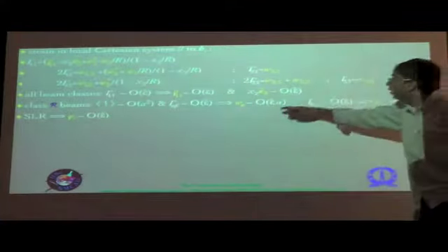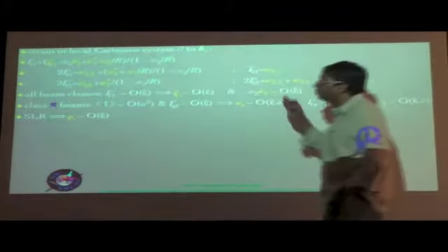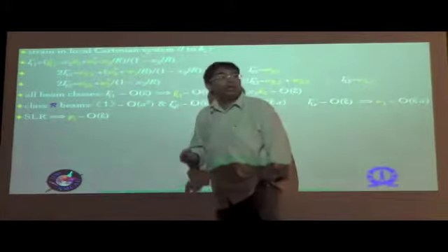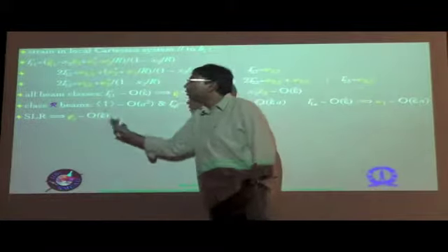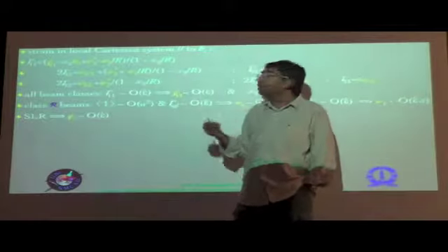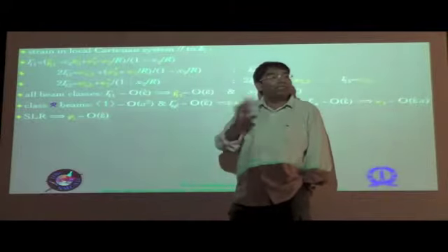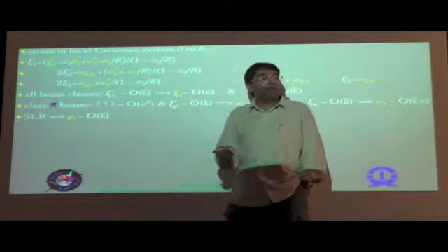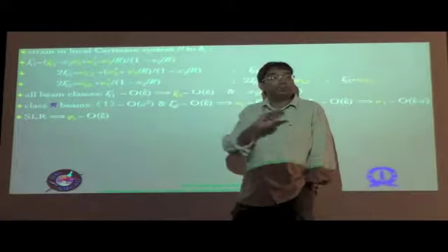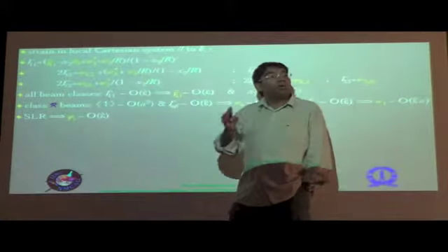So in other words, we can combine all of these. W alpha is of order epsilon hat A and W1 is of order epsilon hat A. So we can just write Wi is of the order of epsilon hat A, which is the case for class R beams. Next situation is the small local rotation, that is of the order of epsilon hat. In fact, this we already discussed in the general situation where we compared the orders of magnitude of the local rotation with the strain, and we took two cases there, if you remember. One is of the order of epsilon hat, the other is of the order of epsilon hat power half, as the two extreme situations where we had small and moderate local rotation.